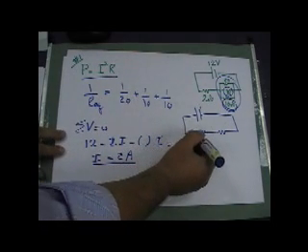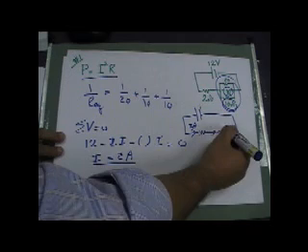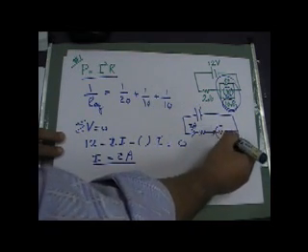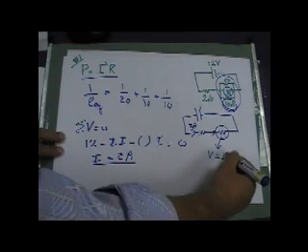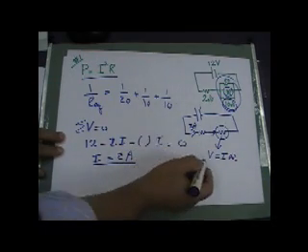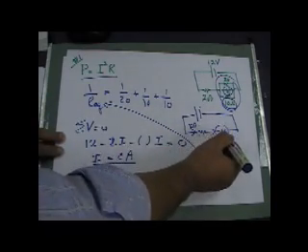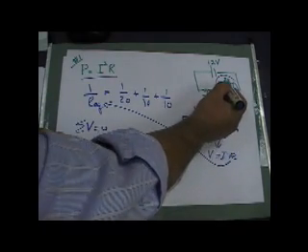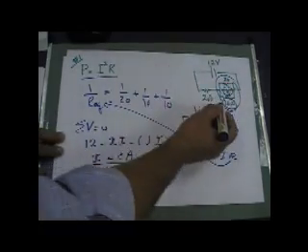So the current here is 2 amps. That means I can calculate V in this combination. V is equal to I R, and R is this R equivalent. Once I do that, the V that I calculated is the same for these 3 resistors, as I said earlier.